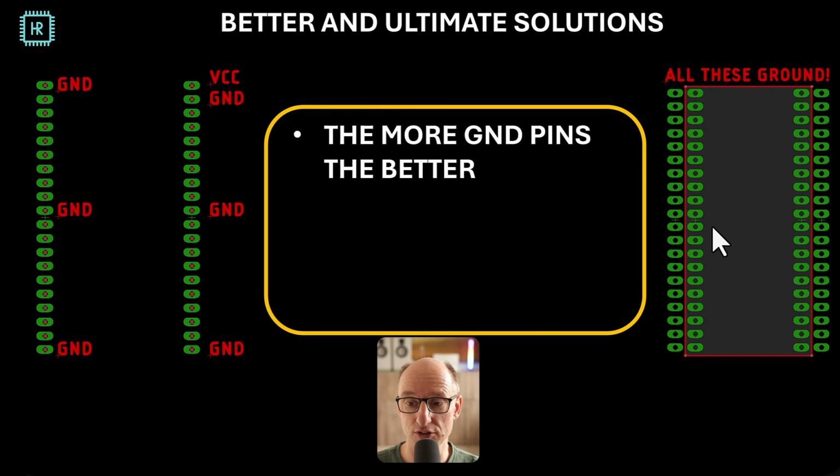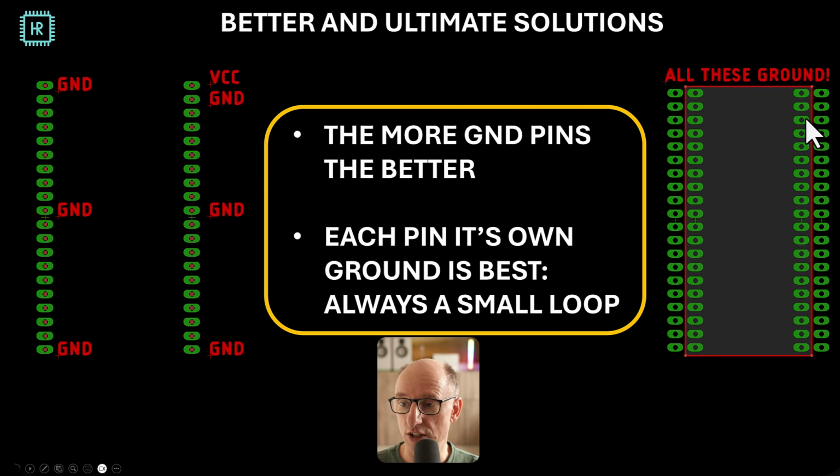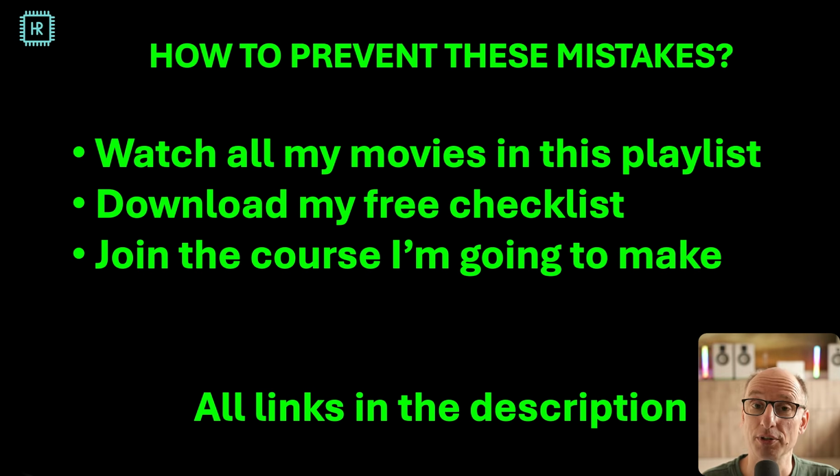So what's then the ultimate solution? Well, we see that on the right here. You give each signal pin its own ground pin. And this way you ensure that the ground return path will always be very short and you have perfect signal integrity and minimum interference.